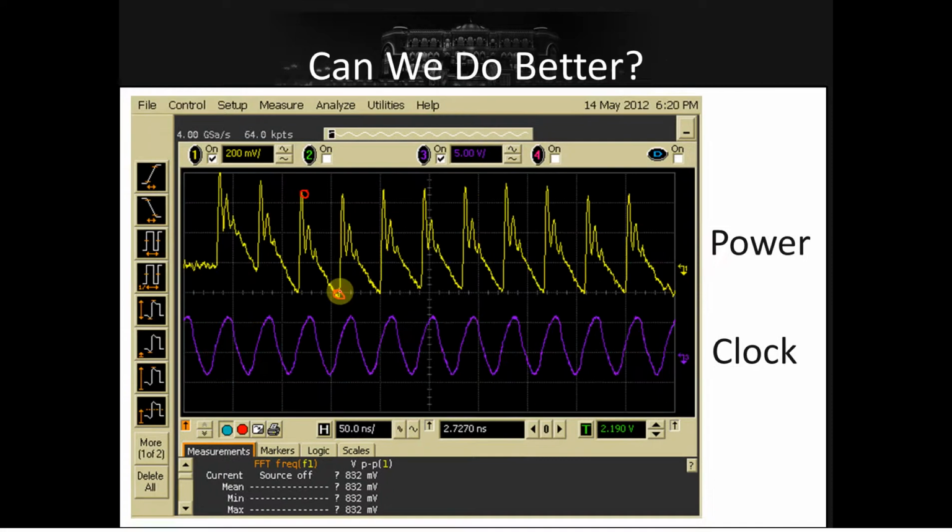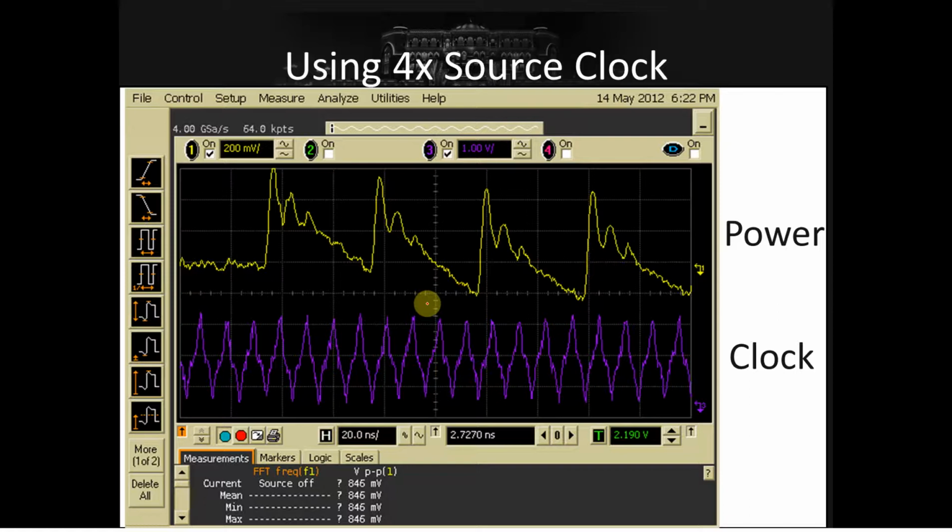So instead, what I've sort of done here, and some oscilloscopes support this, most don't, is you sample synchronously. So you take the device clock and you say, use this transition here to decide when to sample. And you'll always end up sampling at the perfect moment. The thing is, now you're sampling based on when the device itself is going to be moving data around. And that's the real advantage of this technique. And I actually sample at 4 times the clock of the device under attack. There's no actual need to do this.